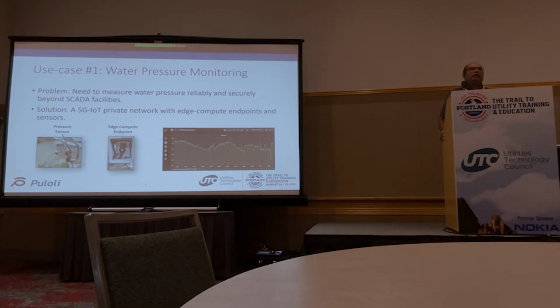So between broadband and NB-IoT, I can give you the answer in terms of link budget differences. I believe it's close to about 20 dB or so difference. So LTE baseline is about 140 something MCL, maximum coupling loss, and NB is 164. So there's about 24 dB difference, I think. So that translates into distance. You can translate that into a distance based on which frequency band you're deploying. So that gives you quite a bit of range.